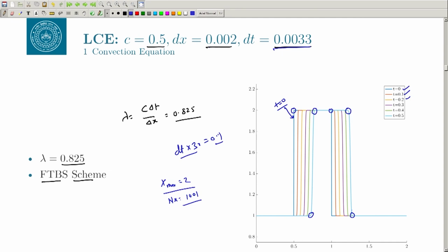Okay, and we have to basically estimate what is the numerical diffusion in your equation. That is a very important parameter, especially if you are going for a high accuracy simulation, let us say LES and DNS. If you are using a very dissipative, very diffusive scheme, then it is likely that you will not get the very accurate solution.